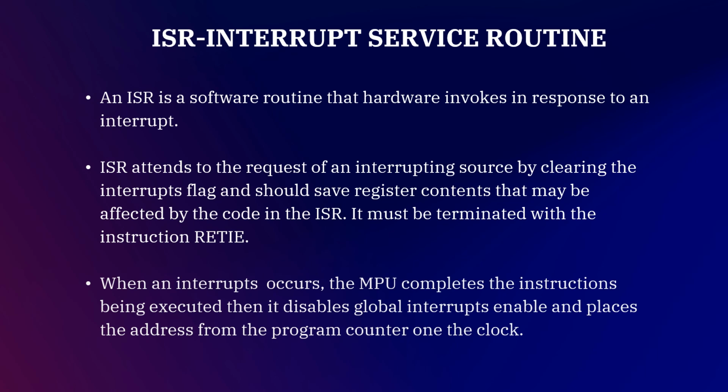Next one is ISR. ISR means interrupt service routine. ISR is a software routine that is hardware invoked in response to an interrupt. ISR attends to the request of the interrupting source by clearing the interrupt flag and should save the register contents that may be affected by the code in the ISR. It must be terminated with the instruction RTI, return from interrupt.